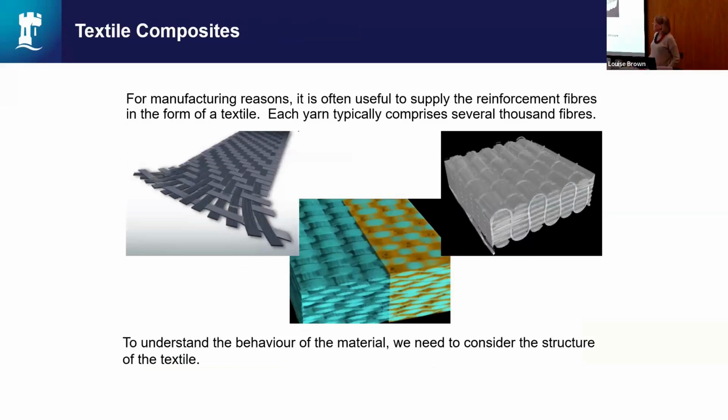Basically because a lot of the time, they're easier to handle than fibres that are unidirectional ones that are just sewn onto a background. So you get things like the one on the left, layers of carbon fibre, and typically they're laminated and made to form a composite material.